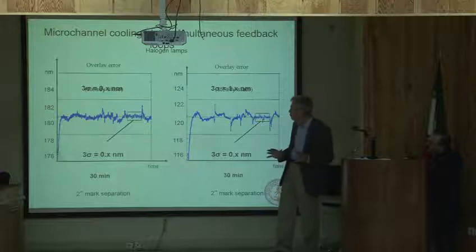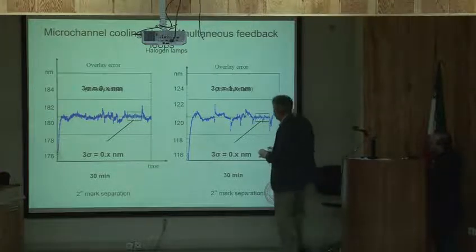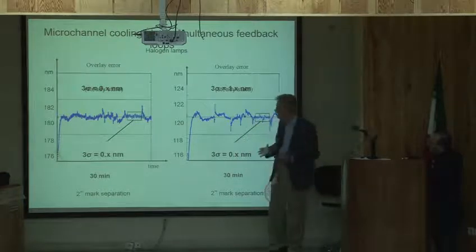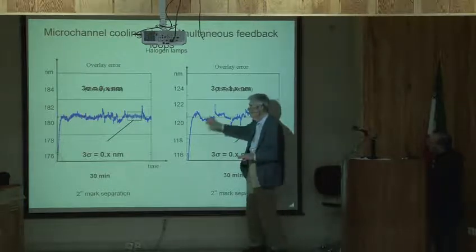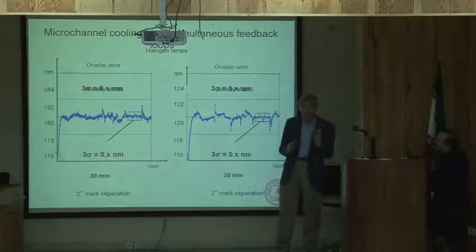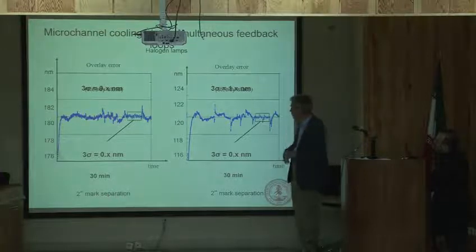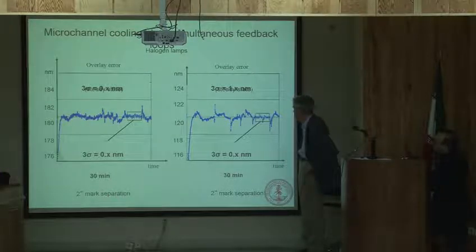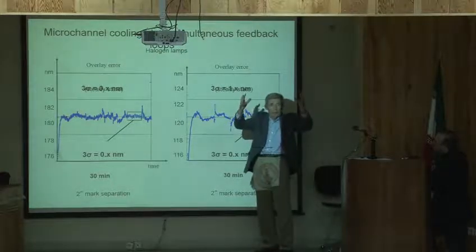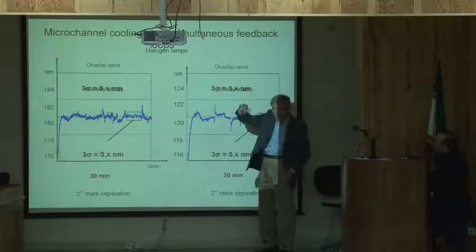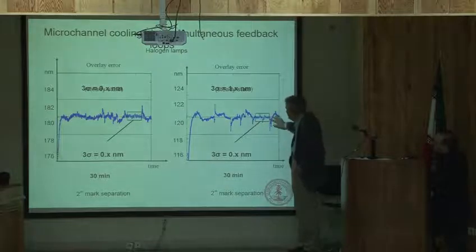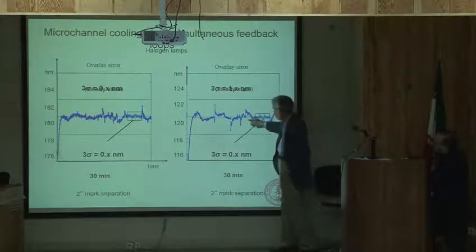I'm not sure if in this country you have water coolers the way we do. But our problem was when we first used a pump to pump the water through the microchannel heat sink, that caused enough vibration that we couldn't use it. The water flowing, when it's pumped, the little pressure pulses look rather like an electrocardiogram. So then we made a gravity feed using a water cooler on top of a cabinet and just had it going through our microchannel heat sink, and then we tried the experiment, but we were still getting little blips.